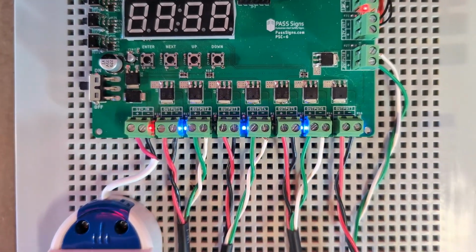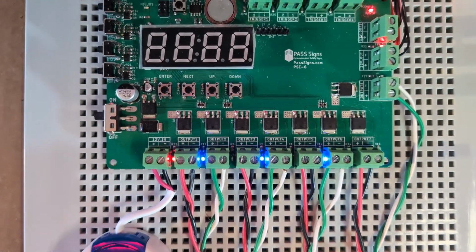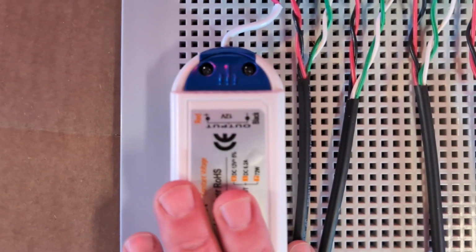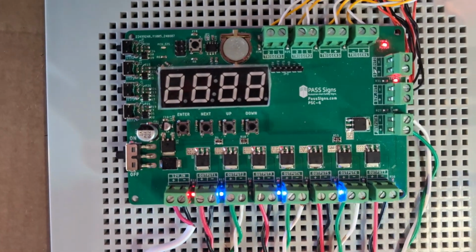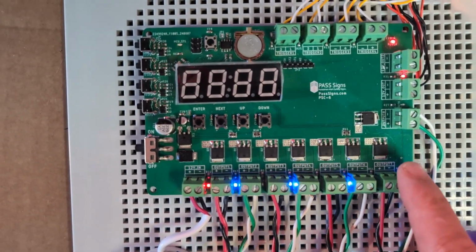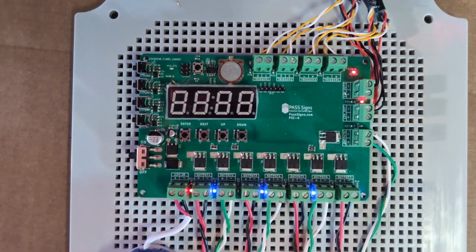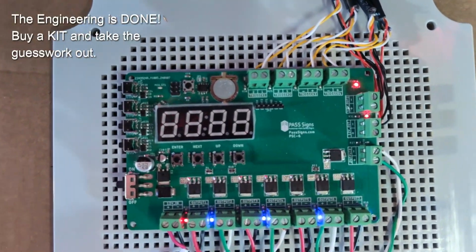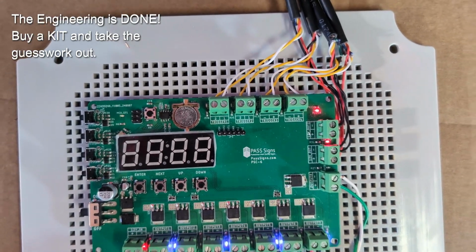Each output is 12 volts DC and can power up to 1 amp. Now, if you're using a 5 amp power supply like this one here, obviously you're not going to get 1 amp on every single output. So remember that. But this is why it's important to buy our engineered kits. They're ready to go. They've already been tested. And they're easy to install for your electrician.